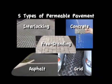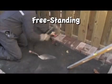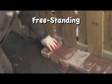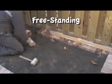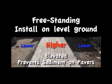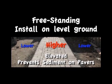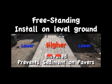The most basic type of paver uses freestanding bricks, concrete blocks, or flat stones laid on a bed of sand and stone aggregate. Of the pavers, freestanding are the least stable and are only recommended for infrequently traveled or light load-bearing areas. A freestanding paver structure should be designed so that the pavers are elevated relative to the surrounding landscape. Elevating the pavers prevents soil and sediment runoff from collecting on the pavers, which may cause clogging.